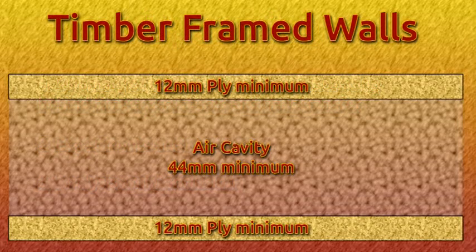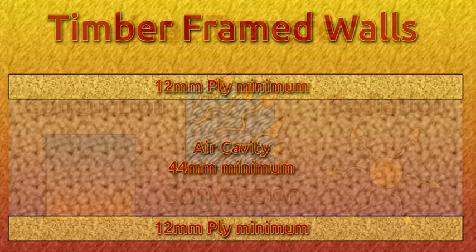To start off with, let me give you a brief summary of how timber frame walls are constructed, as well as how heat travels through objects, also known as thermal conduction. Timber frame walls are usually constructed with timber studs spaced at 450 centers, with ply cladding fixed to the battens to give the walls more strength and thermal resistance. The Australian standards specify at least 12 mm ply thickness for thermal resistance. These experiments are designed to determine if this is enough.